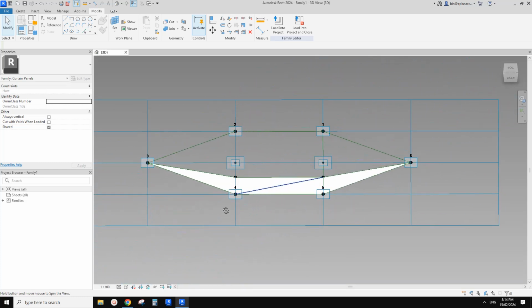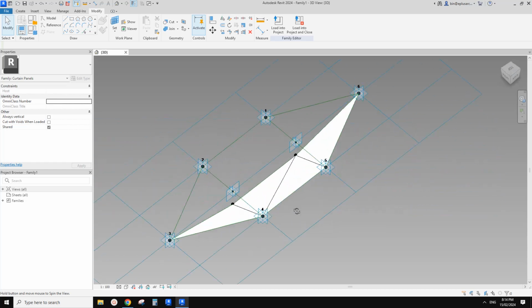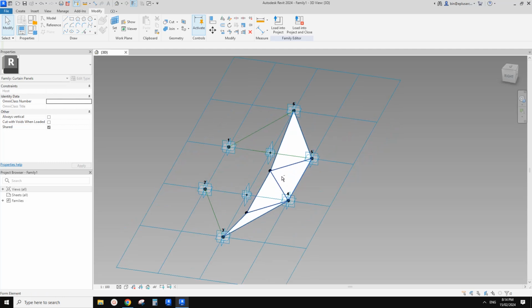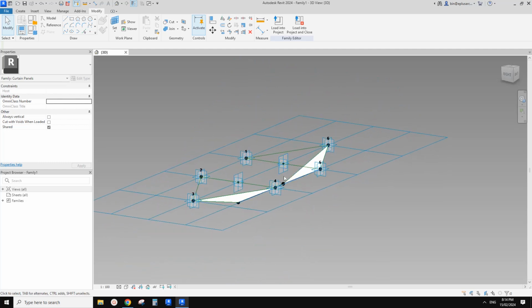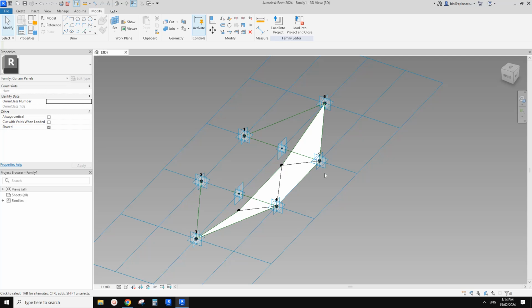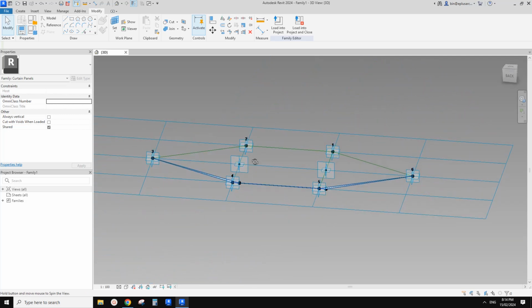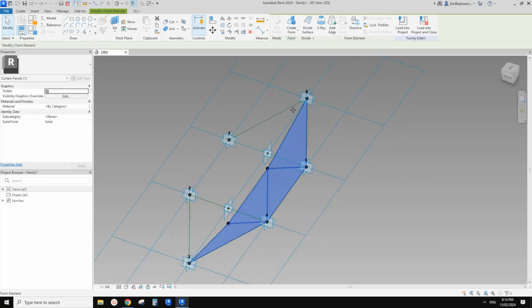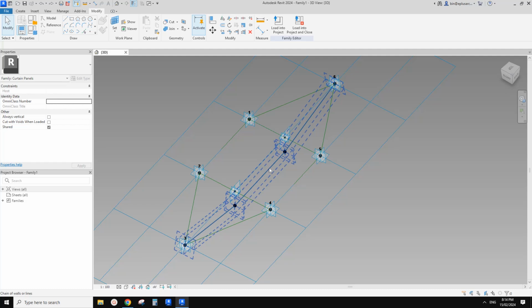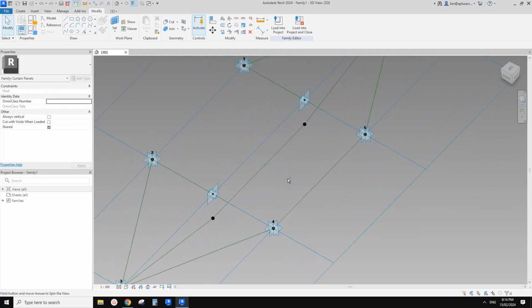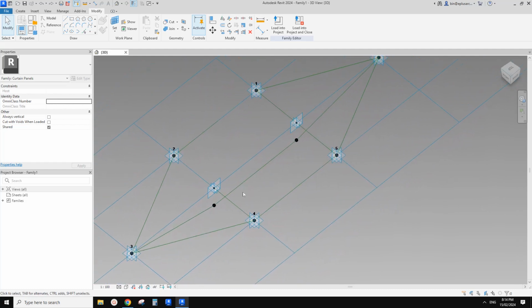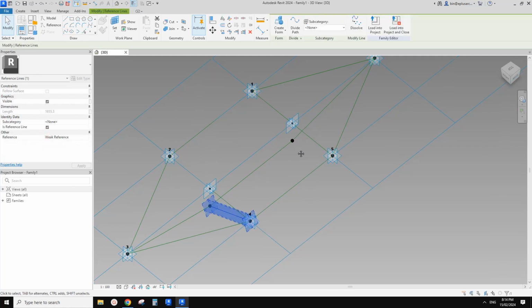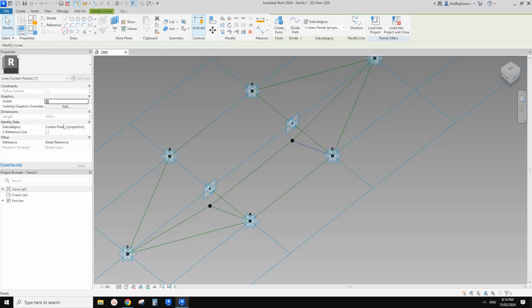But this edge, I think we probably don't want to see this line, because these 4 points are supposed to be in one plane. That's fine. Maybe let's just Control Z. So instead of 1 2 3, we can create them separately. Let's place another spline through points between these two, and also another spline through points.